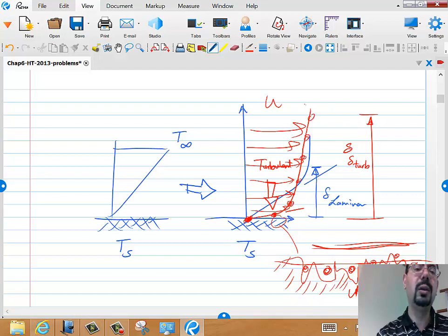But what is the mechanism? Mallory is saying it's because the first layer doesn't want them to move that quickly. What do you call this interaction between the layer stuck to the wall and the next layer, which is not allowed to move that quickly? That's the friction caused by the viscosity. That's the viscous effect. It's the sticking force between layers, and the more sticky the fluid is, if it's honey, it will behave differently from ethanol.